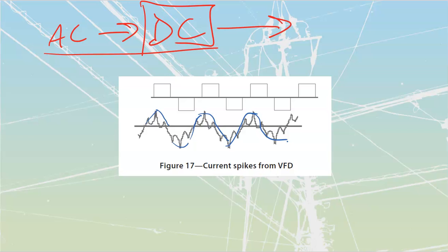We're going to deal with those later on, but before you even start that, you have to start by just doing a walkthrough. A lot of it can be identified just by the load types and by the timings. Go through, get as much information as you can as to, first of all, what the issue is. Then try to develop an accurate one-line diagram of the entire thing. A one-line diagram is just going to show where you've got your incoming power.